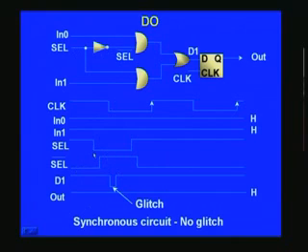So here, of course, there's a delay, and this gate delay is because of this inverter. If you see the output here at D1, what happened? It is nothing but ORing of this. Since IN0 and IN1 are 1 each, whatever you apply here, that is select bar and select, will appear at the respective ends, and when ORed, you get basically this.